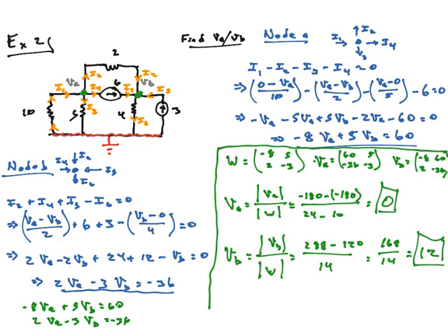Interesting, one of the voltages happens to be 0, but that's just the way the circuit was drawn, the numbers chosen, things like this. The voltage at A is 0, the voltage at B is 12. Now remember, these aren't the actual voltages at A and B. Those are the voltages relative to the ground being set to 0.